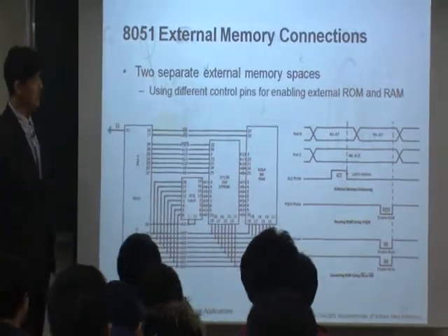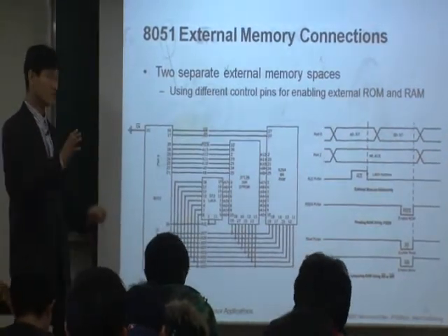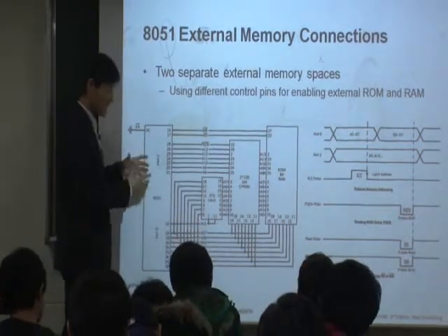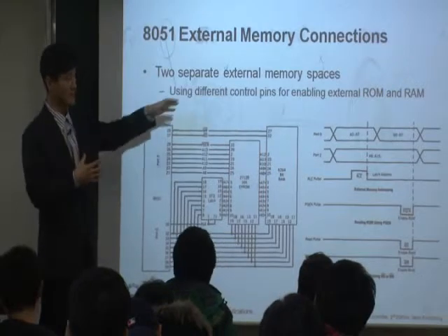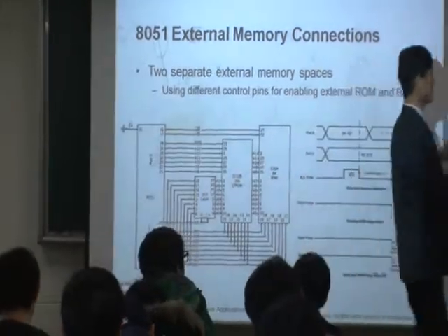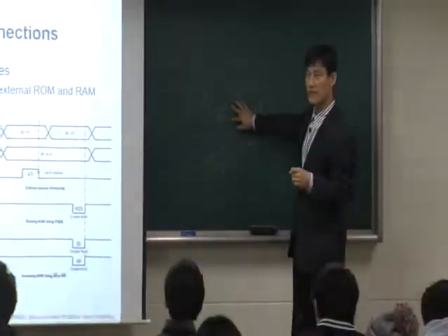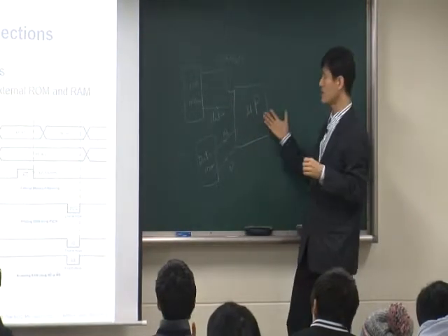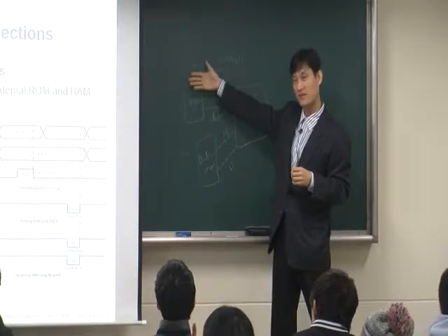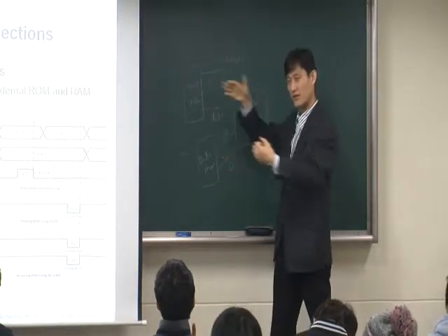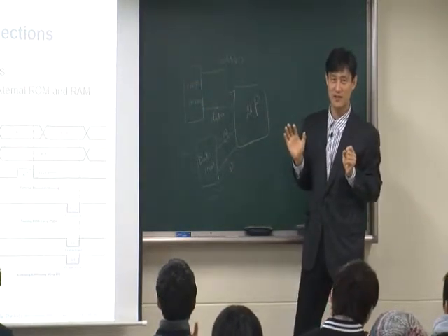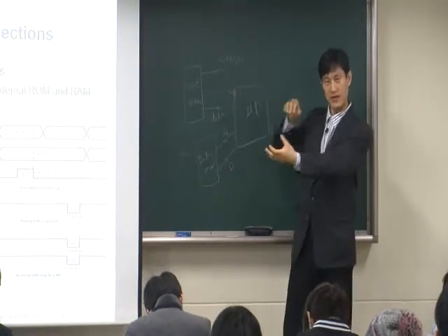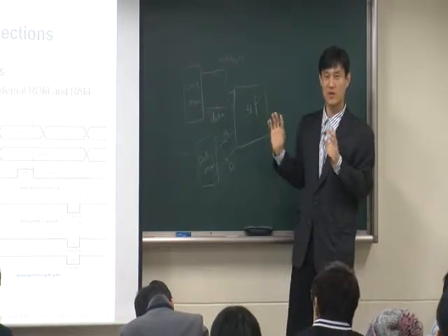So that's the 8051. The message here, the simple thing, is that let's say there's a microprocessor. These days, as I said, we have separate address pins and data pins. In that case, you don't have to do this. You just send out the address, and at the same time you get the data. So you don't need a latch. Send out the address, I get the data, at the same time. You can do that, no problem.